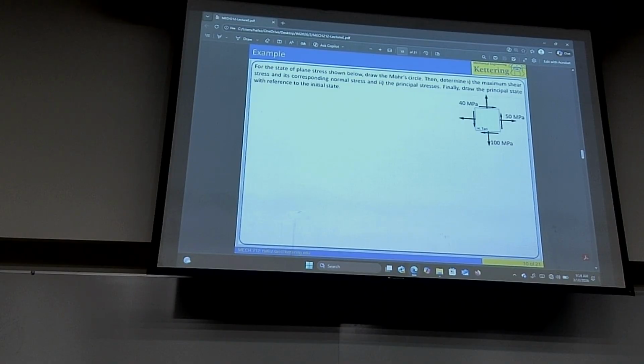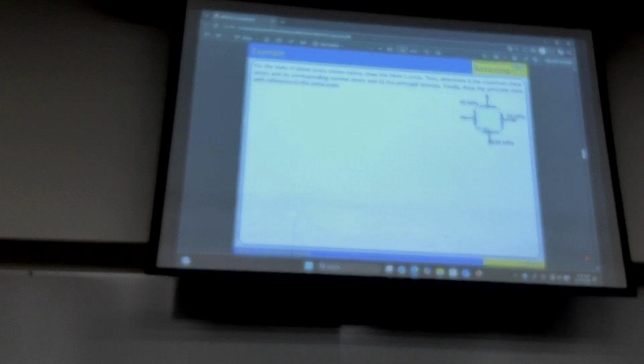No, you give me for cantilever. Jansen should give me the one that you were about to mention. Please prepare. It's FL to the third over 3 EI. All right, go for it. 5 WL to the fourth over 384 EI.